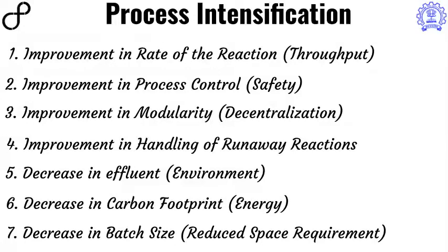It is clear from the above discussion that there are multiple ways by which one can define process intensification. I feel improving the rate of the reaction is the broadest definition, wherein all other definitions are automatically incorporated. Therefore, in our subsequent discussion, we will focus mainly on what is the rate of the reaction, which are the factors which affect the rate of the reaction. We will then discuss the main limitations of batch technology, which prevent the ultimate process intensification, and how these limitations can be overcome using continuous flow chemistry.